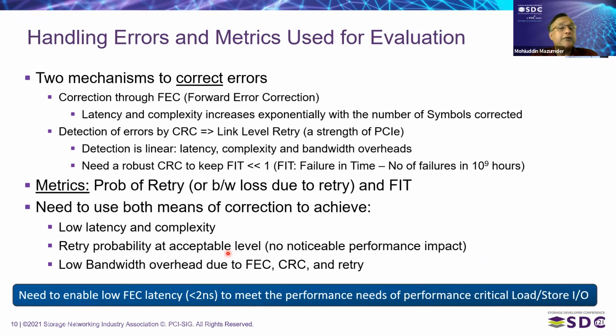So instead of, again, focusing on minimizing per lane effective BER with a very robust and heavy duty FEC, we are looking at the metric of failure in time, which provides us similar reliability as previous gens of PCIe, but relieves us from the requirement of having a very low effective bit error rate and the high FEC latency.